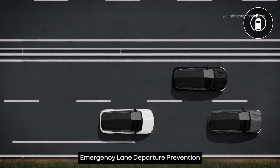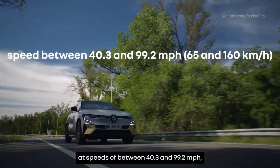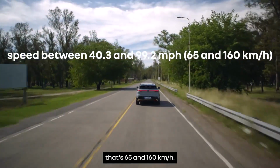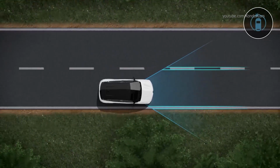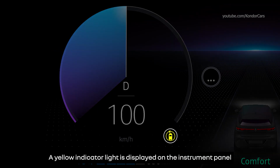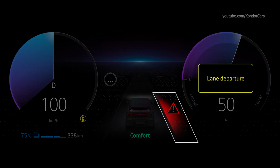Emergency lane departure prevention can detect an approaching roadside at speeds of between 40.3 and 99.2 miles per hour, that's 65 and 160 kilometers per hour. When a collision risk is detected, the system corrects your trajectory. A yellow indicator light is displayed on the instrument panel with this symbol and the message "Lane Departure."